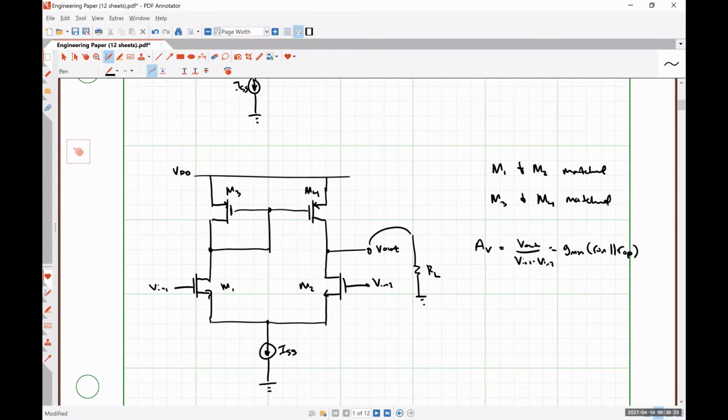The only difference between this gain and what we would get from a differential pair, where we were taking the differential output, would be that we no longer have an inverted input. It supplies the exact same amount of gain. So it has identical performance, but we now have a single-ended input, which is what we would expect for an op amp. So in essence, this is literally the most simple op amp you could ever design.